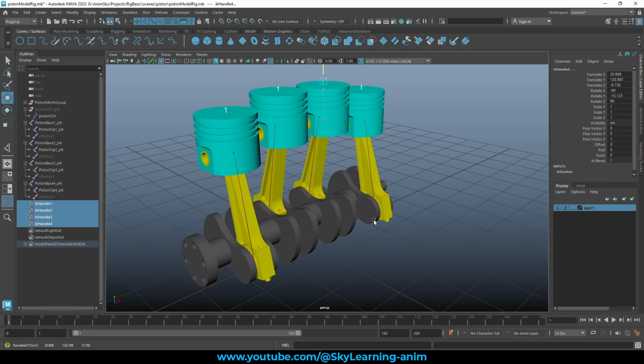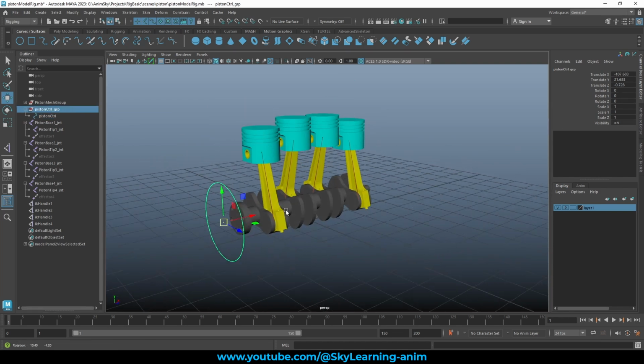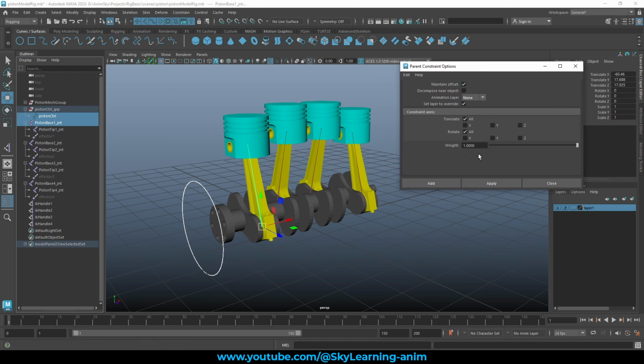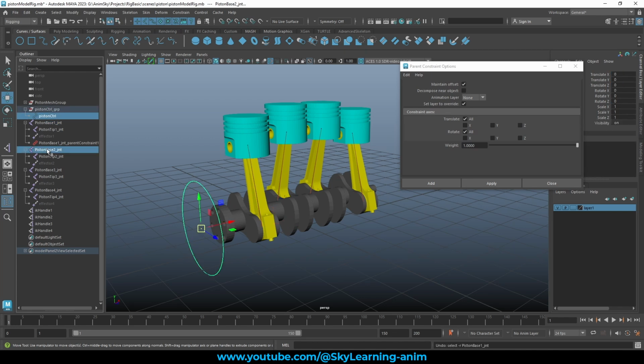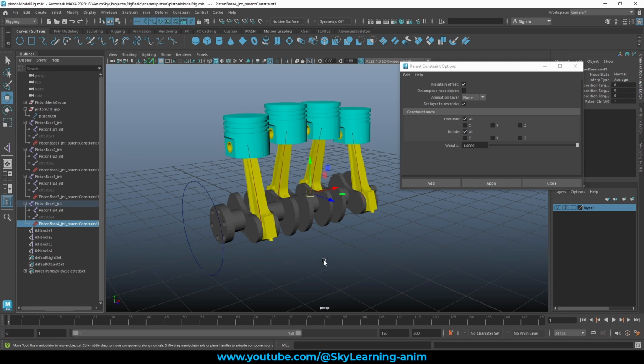So this is now acting great. This is what we wanted actually. Now is the time to turn on the parent controller, select the parent controller and do the parent constraint for each of the base joints only. So constraint parent, and maintain offset on, make sure. So do this for this one, press G, select this one, press G. Remember, I'm only doing the constraint with the base, not the tip. G, and I guess we have 1, 2, 3, 4. All 4 base joints are connected.